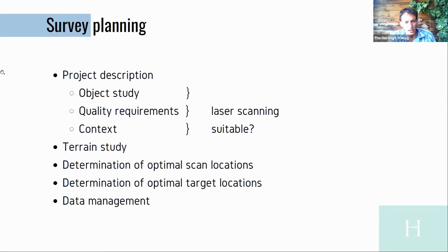correctness. And even if it is not possible to fine-tune these quality requirements, I believe that it's the task of the master of the 3D technique, so the master of the data acquisition and the processing, and the person who is involved in the deliverables, at least to steer the discussion by saying, okay, if you're not able to define your ground sampling distance or your point density, what do you think about these densities or these quality measures, so that at least you're able to steer that discussion.